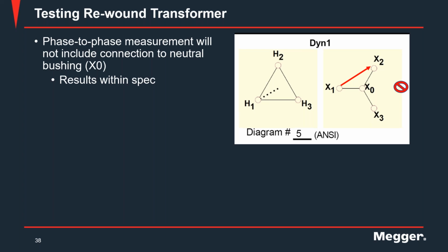and they are used and trended over time to determine any possible issues with your transformer winding. One note about excitation current is that it's typically performed on the high voltage winding of the transformer by keeping the low voltage winding open circuit. So now you're only concentrating on the amount of energy required to establish that working flux in your transformer. So it's done, but it's done using AC quantities, which is known as the excitation current test. Thanks.